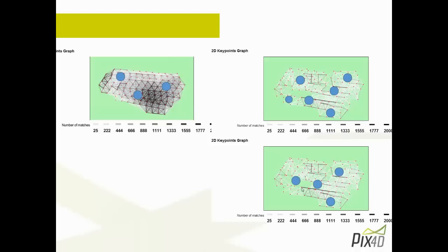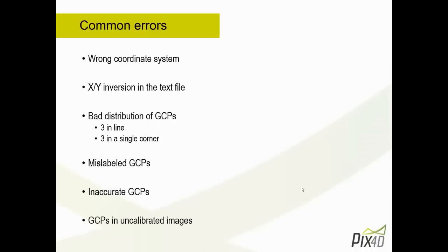If you had the choice between adding more GCP and taking the images with better light condition, more overlap, more data, you should always go for more data and better light condition. Adding GCP helps, but it's a complicated way and requires a lot of work to be done, where usually adding more data would solve all of your problems without having to introduce too many ground control points.